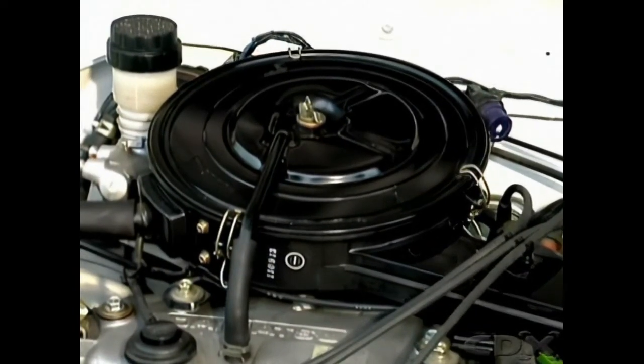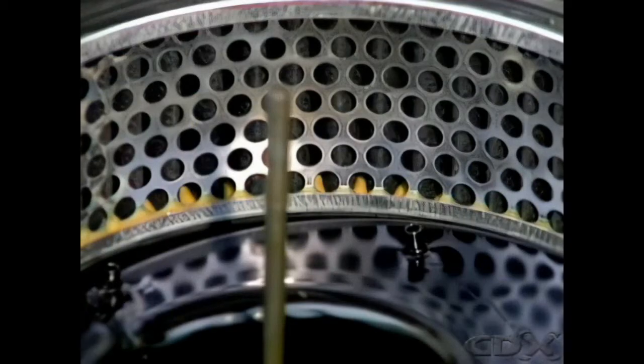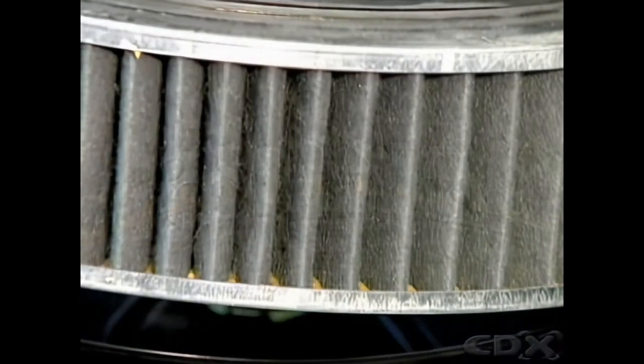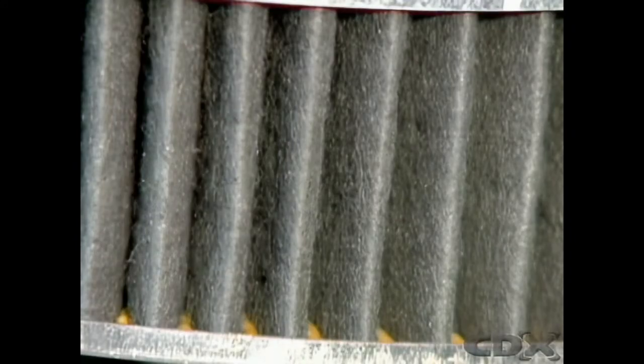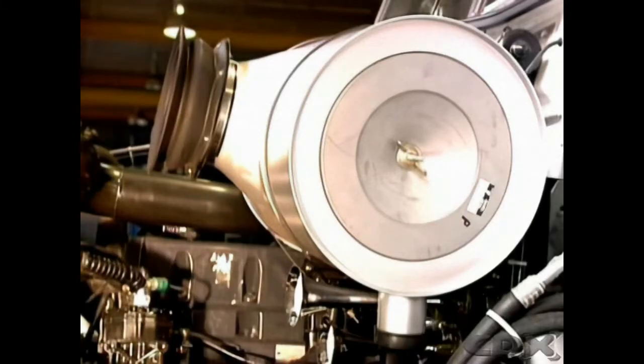The most common air cleaner is called a dry element type. It has a replaceable dry element of pleated paper or cellulose fiber that doesn't need to be wet or use oil to act as a filter. The paper is pleated because that gives a much larger surface area in the space. The element is designed to be fine enough to trap impurities, but porous enough to let air through easily.